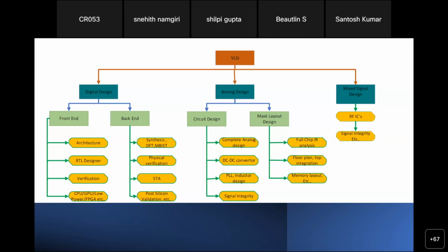If it will not sync, your processor is useless. Okay, so we need to do the silicon validation also, that is called post silicon validation, where we used to test all the interfaces, whether my camera is working or not with the processor, whether my USB is working or not, my keypad is working or not. Okay, there are many interfaces. So this is also a good option. This you can also apply.